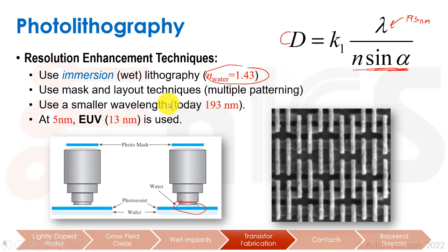But when we went to deeper technologies, we started to use multiple patterning. That means we use several masks and shift between the masks, or we use self-aligned double or quadruple patterning, which I'm probably not explaining much in this course. But that is what we actually do in processes such as 16 and 7 nanometers to get really closely spaced pitches.